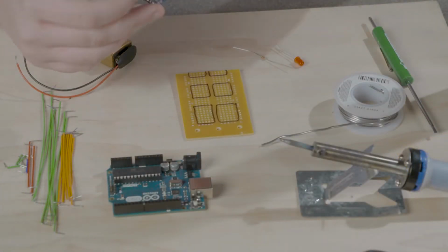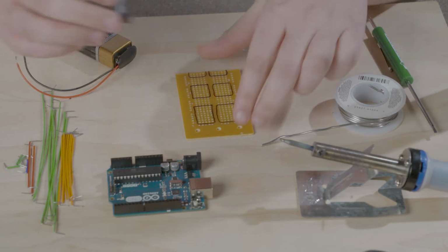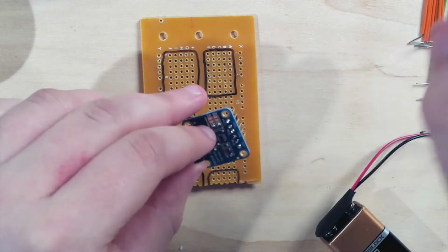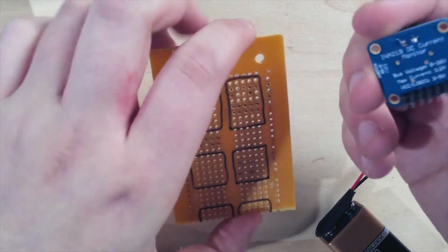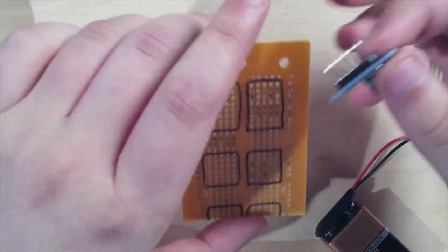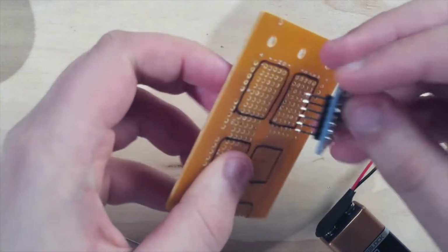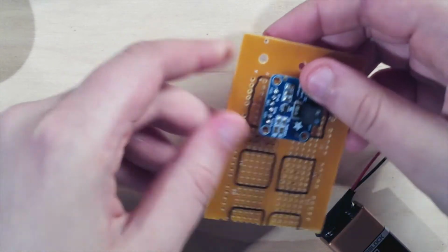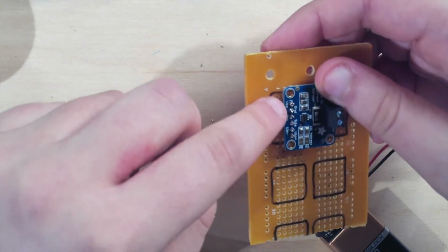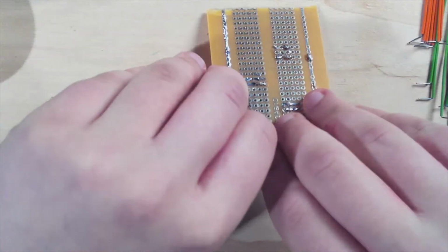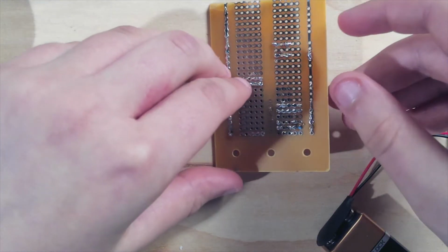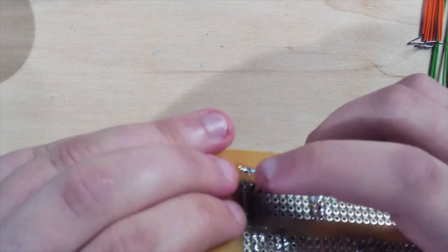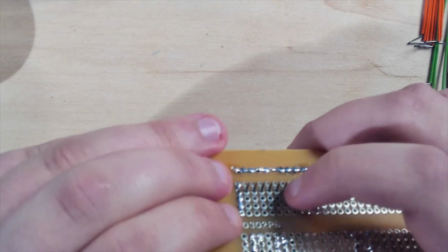All right, now that we have the current sensor soldered, we're going to add it to the breadboard and have a series circuit connected to this and have all the wires go into the Arduino. So let's take our current sensor with these little prongs here. See where we should put it. Let's put it here. Make sure there's holes next to these pins because those are where the wires are going to be connected to. So turn it over and let's solder each one of these pins. Make sure that none of them connected to each other, only on the row of the circuit board.